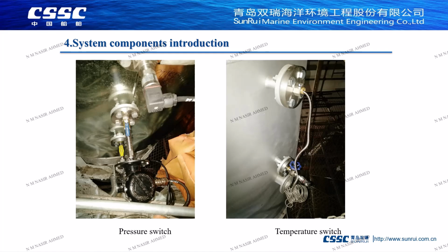If the temperature of the discharge is too high, it indicates that the exhaust gas has not been cooled or washed. At this time, the high-temperature exhaust gas will cause certain damage to the desulfurization tower. So we install a temperature switch and make a hardware scram, to prevent smoke from entering the tower in the event of a system failure.